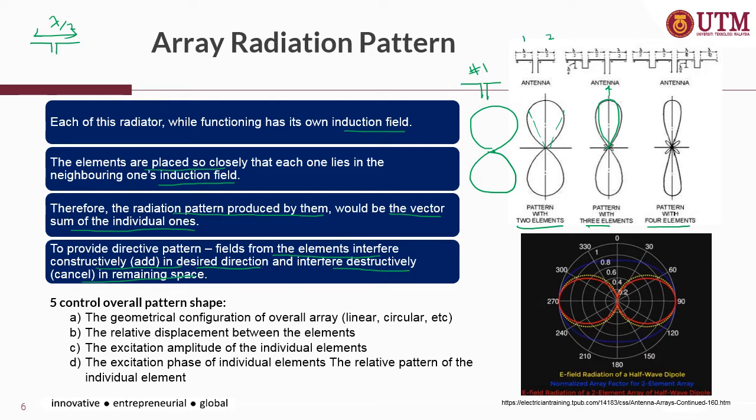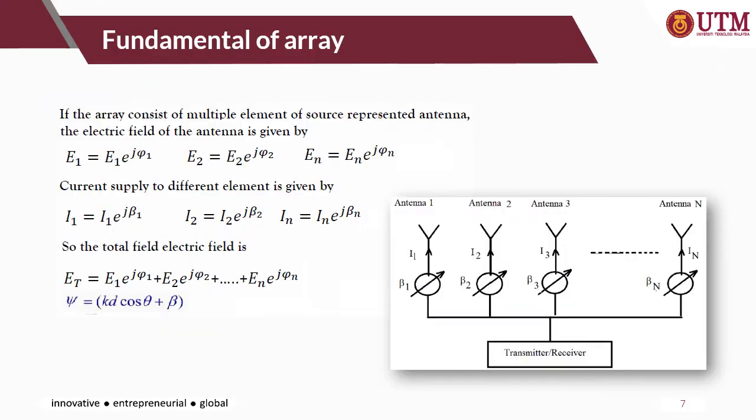So we can control the overall pattern by controlling the geometrical configuration of the array, and then the relative displacement between elements, the distance between elements, the excitation in terms of the amplitude, and also the phase of excitation. Okay, this is the fundamental of an array.